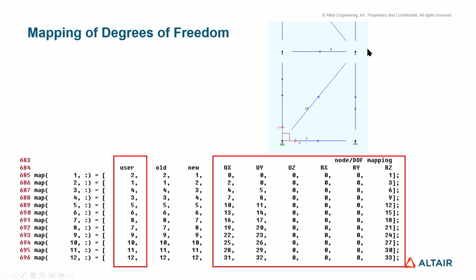And if you remember, we applied the 2D constraints, which basically constrained all the other joints so there is no displacement perpendicular to the page. And then there is no rotation about the global X and the global Y. So that's why these are all zeros. And then the rest, again, it gives you basically the row and column number for that degree of freedom.